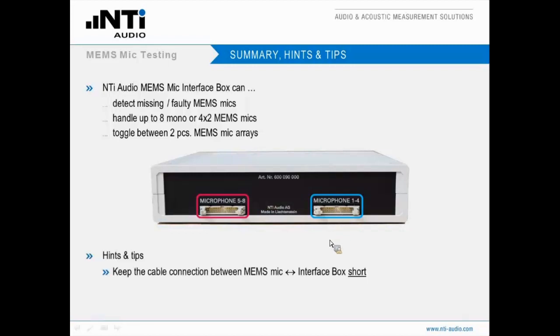Keep in mind when you connect the box to MEMS mics to keep the connecting cable short in order to avoid data loss or any other kind of problems. So this is something that you should keep in mind. And also, as stated before, the higher the clock frequency, the higher is the power consumption of your MEMS mics, but also the audio quality. That is up to your decision in which range you want to work.